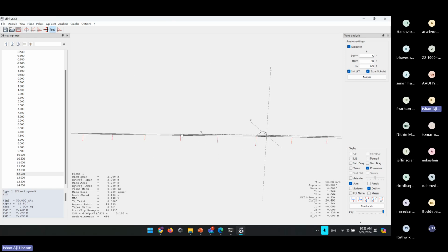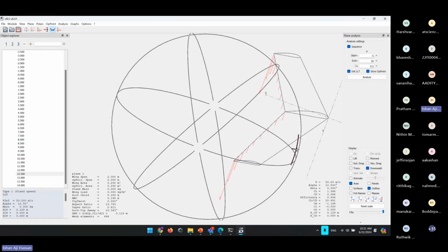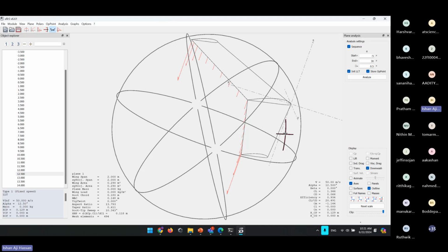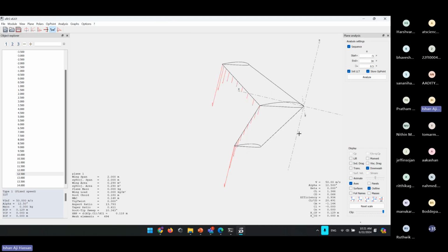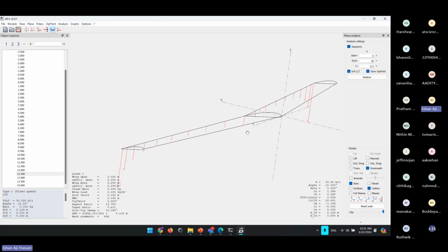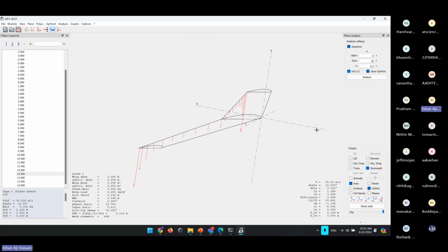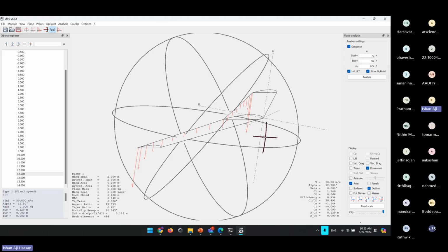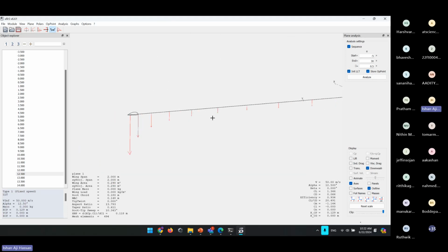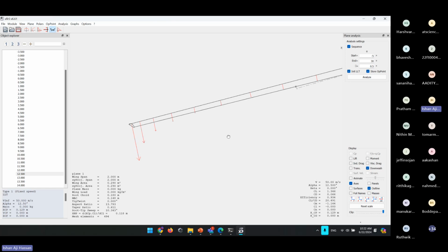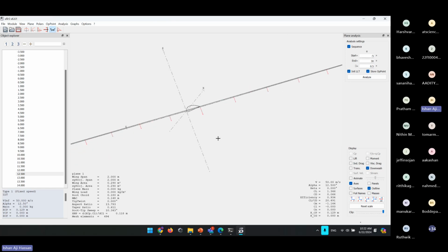This red arrow is basically representing how far the air is going down, how far downwards the air is deflected at any particular wing section. Like I said, airfoils basically deflect the air that is coming in one direction to a direction that is further down from them to generate an upward reaction force, lift. So here, due to that wingtip vortex, we see that the airflow is deflected much further down towards the wingtips as compared to the center and everywhere else.